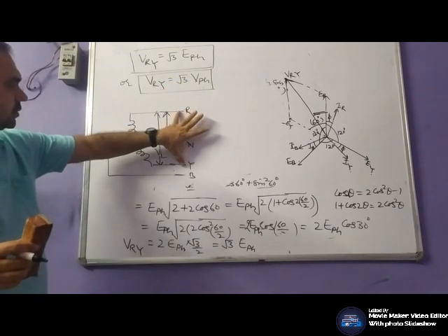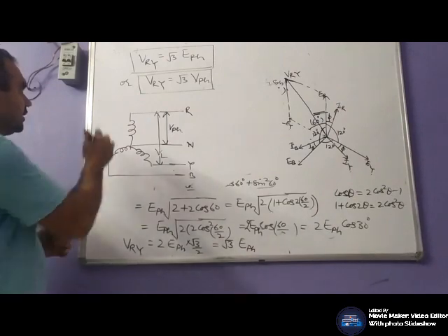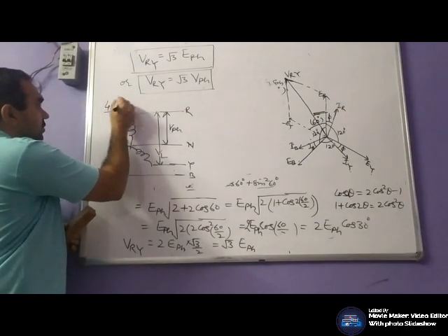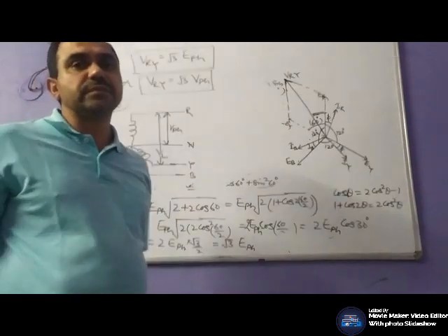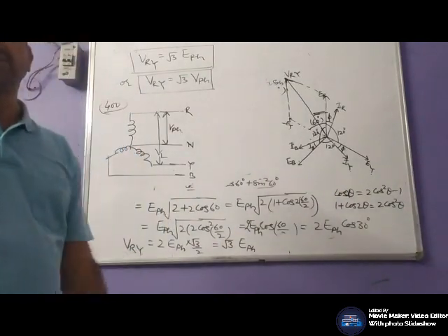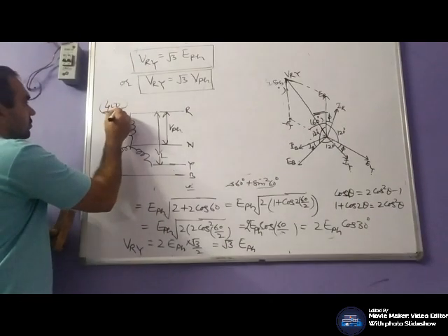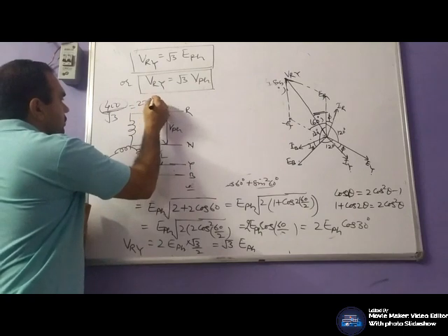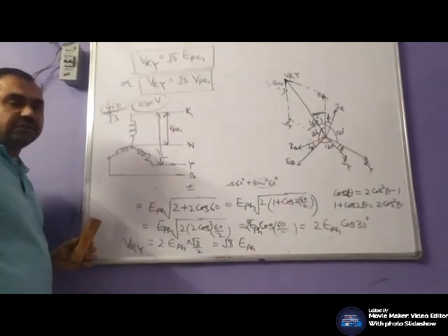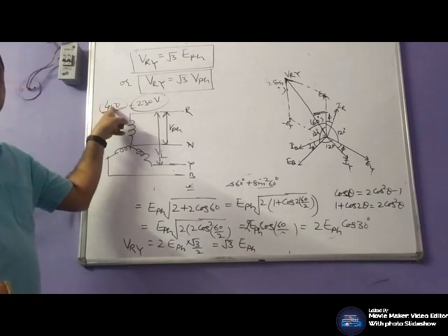If you measure the voltage between 2 lines, you observe that the voltage is 400 volts, whereas your household appliances require a voltage between 200 and 250 volts. Now if you divide by root 3, it will be around 230 volts. Means if you have 3 phase, your voltage is 400.